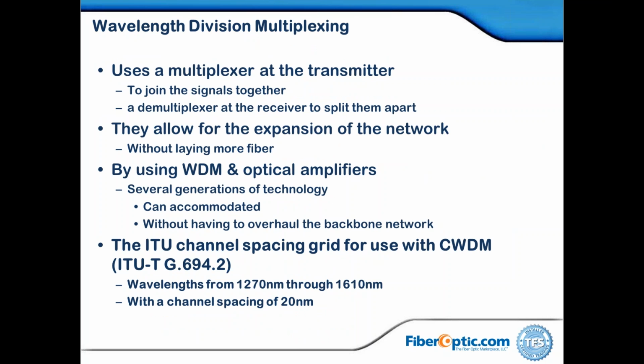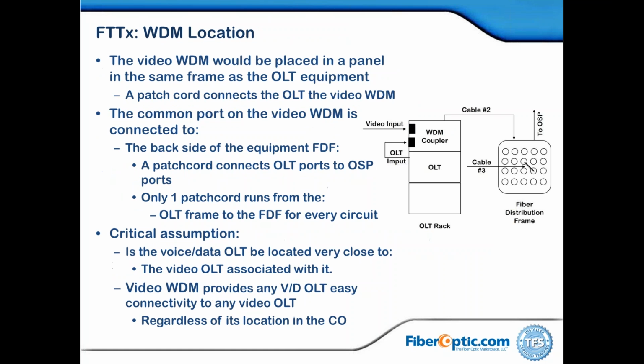and we can communicate. Now that brings us to a basic thing of fiber to the home, is the fact that I can downstream video and at the same time uplink my other services over a single fiber. The fact that the upstream services aren't running on the same wavelength means that they will not interfere with each other. Now later on, since typically they might split to 4 homes off of one fiber as they come down your street, that means if I'm troubleshooting one house and trying to test upstream through the splitter, my OTDR can interfere with other subscribers, say downstream video signals. So how you test this is important, and what you test it with is important.